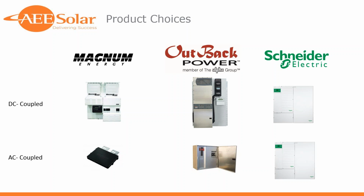I'm hesitant to include any information on which PV inverter manufacturers support AC coupling because that can change. I've got kind of a back of my mind list that I refer to on products that I've known to be approved and in good working order, but it's maybe not anything I want to commit to paper and be responsible for a failed warranty claim. So we've got lists we can maybe tell you about, and you can go do your homework on what's approved and what's not.